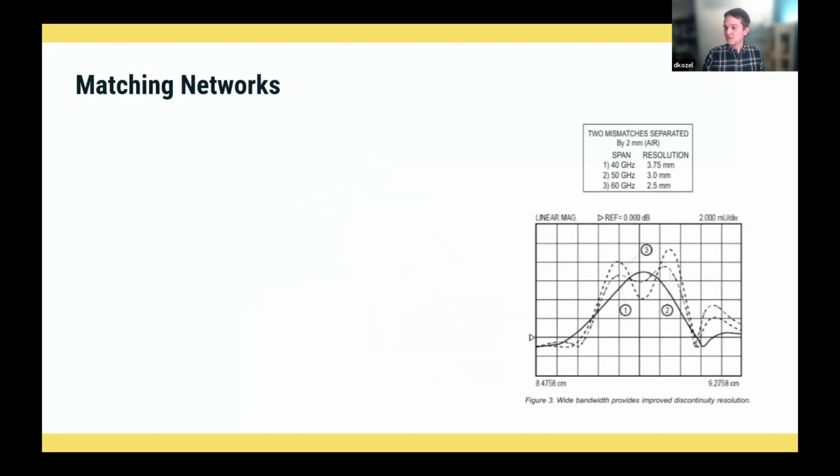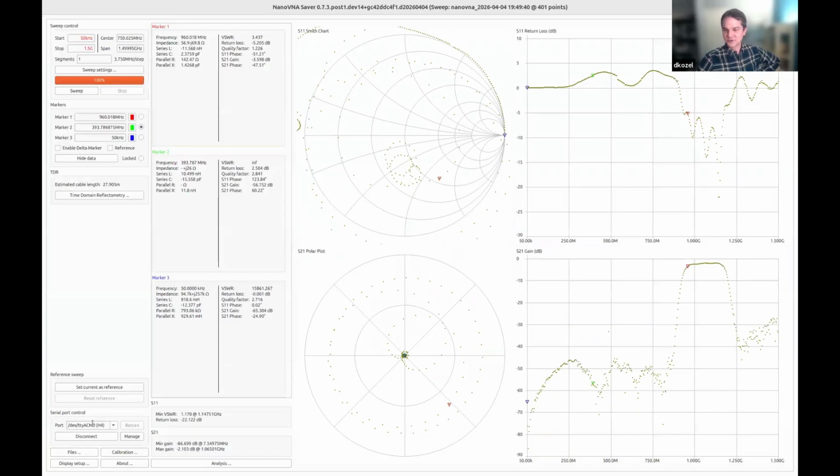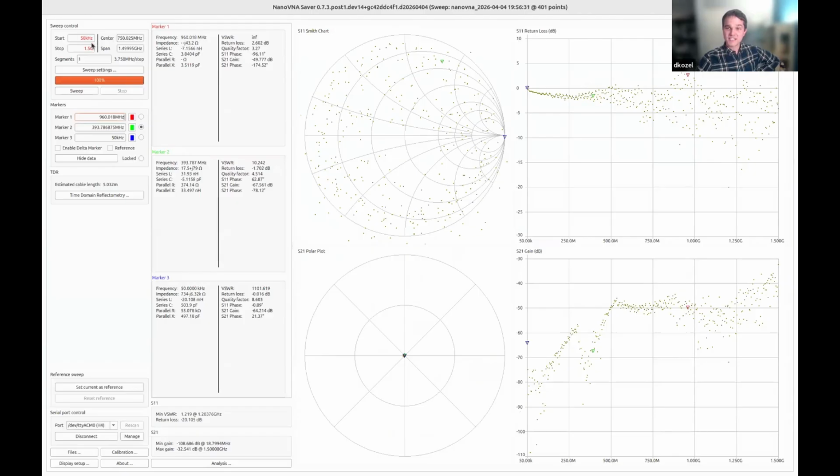And so, propagation, the comments in chat: propagation delay, knowing the velocity factor of the coax, you can find the breakpoint. Yes, you can. I will do one more sweep here. I'm using the maximum kind of usable range of this VNA.